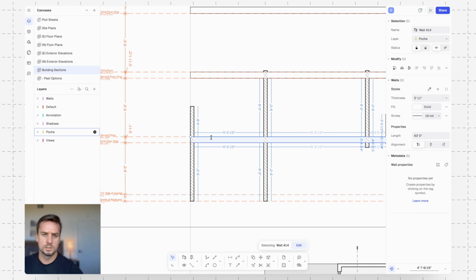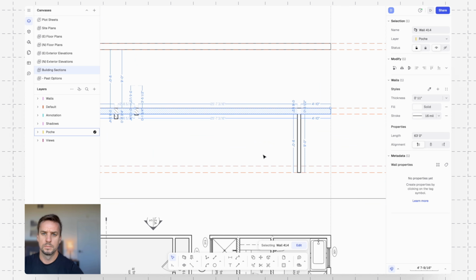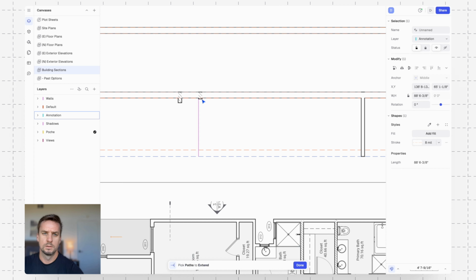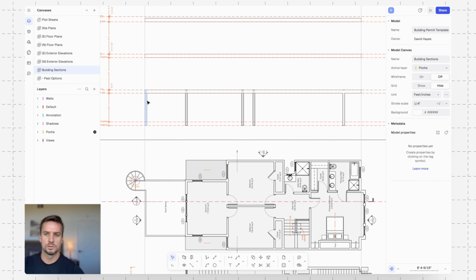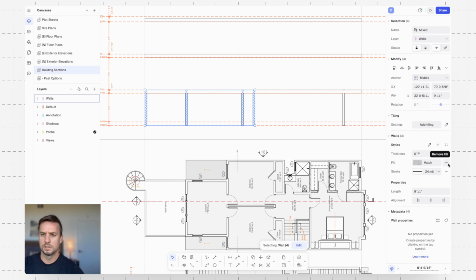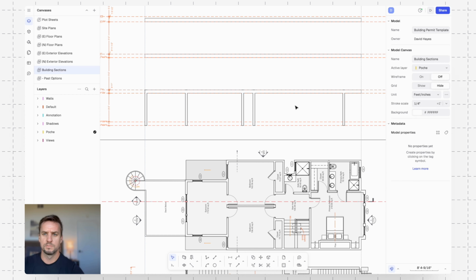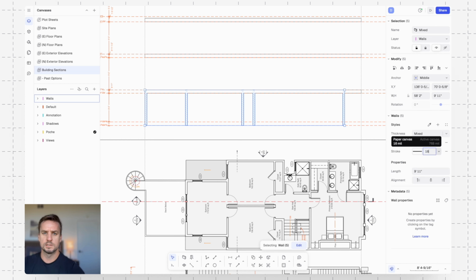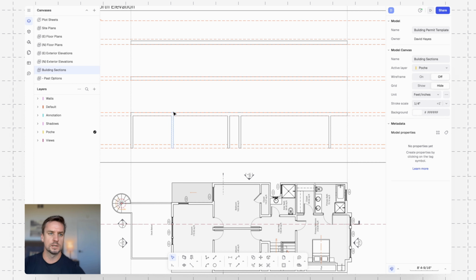And I want this to trim. And maybe for these ones, I don't want it to show that hatch. So maybe I'll just select all of these, and I'll just switch to a solid white fill like I have on everything else. And it looks like the line weights might have also carried through here, so there I'll do that 16 as well.